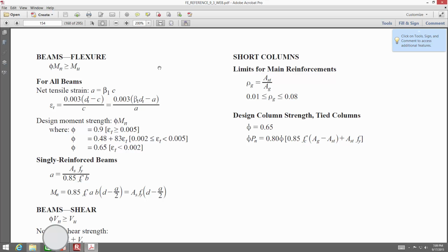So the last edition of the manual that listed more formulas, I mean, it had a whole lot more. It had doubly reinforced beams. It had conditions for whether or not the steel yielded, or whether or not the compression steel yielded. There were T-beams listed, whether it was a true T-beam or a rectangular T-beam. Remember, that's where the depth of your stress block is. All that stuff was listed, and it's not listed anymore, which really means one of two things.